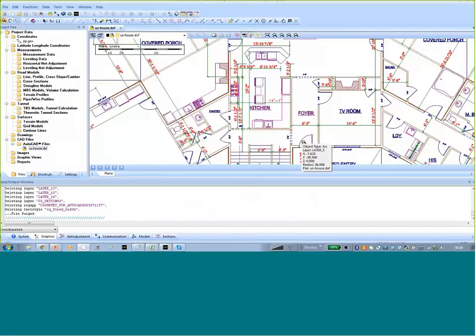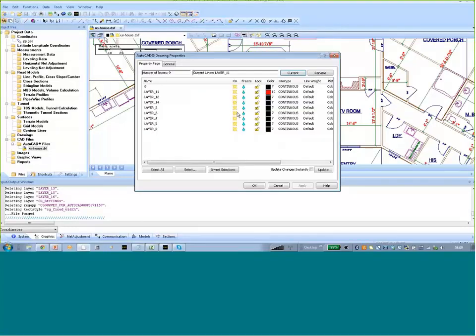Now, just to show you the makeup of this particular DXF, there's 7 or 8 layers here after Clean for Field. So there will have been a few more layers, like unused layers, that have been removed as part of that purging process. What I'll do is I'll export all these layers turned on. But incidentally, if I did export this file to Icon with some turned off, then Icon would automatically import the file with the same layers turned off. So you can prepare how you'll view your data even now in the Office. You could turn those layers on later, but that's the way they'd be imported. You can call that active layer identification.